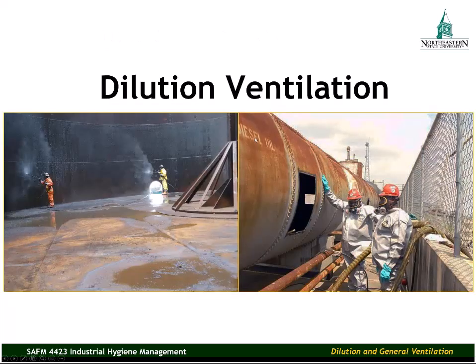Get my pen turned on here so I can make some annotations as we move along. And we have diesel oil. And that's another thing worth mentioning. Anytime you have a tank like this, it needs to be marked what is in it or what was in it, because that will determine the safety measures that need to be taken when you enter that space. Again, diesel oil, if they're entering that space, they need to make sure all of the vapors are purged from that space before it's safe to enter.